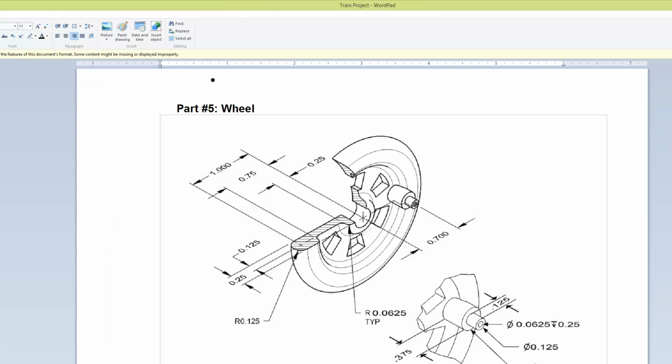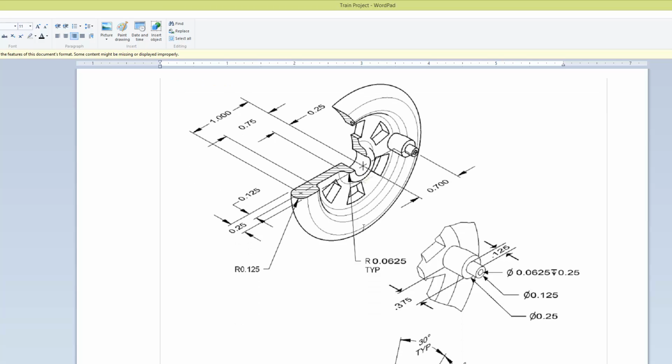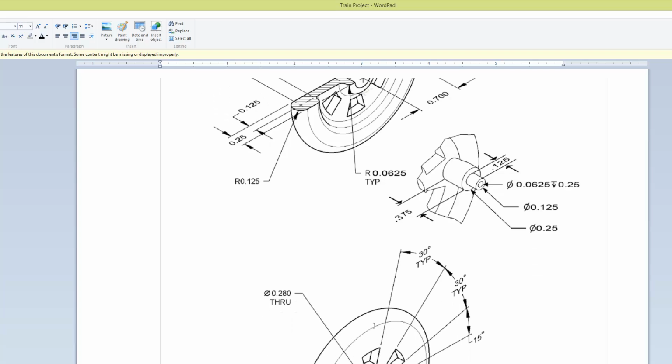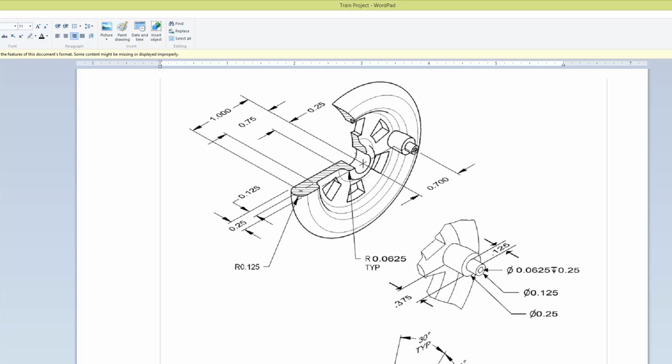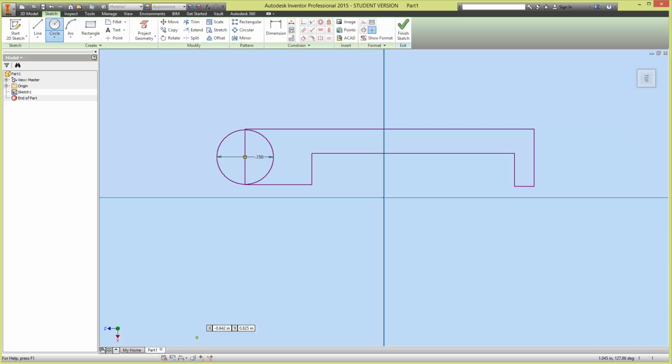If you look over here, you'll notice that there's some open space, and when you revolve it, it creates an opening. So there has to be a line that's in the middle of nowhere that you revolve this part on. So if I hopped over here, I would, let's say, draw a line, I don't know, over here maybe.